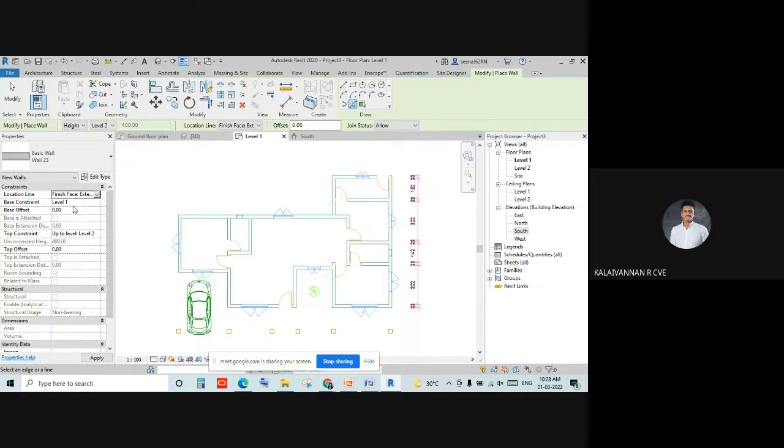No need to create that. If you create the file as a main file, if you want to keep the file as a main file, no need to create a wall from level 1. So you must create the levels first, then create the model walls. Do we need to create different levels now, like a plinth level and all that? Yes. Then after that you can create.